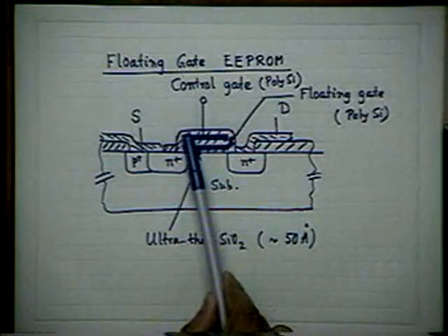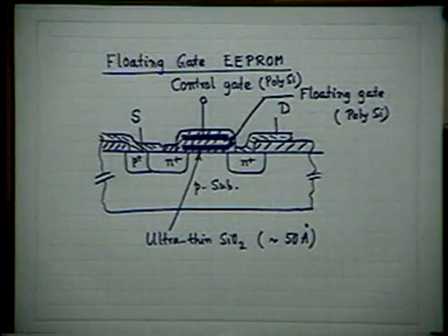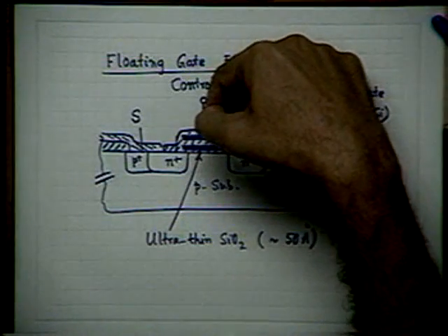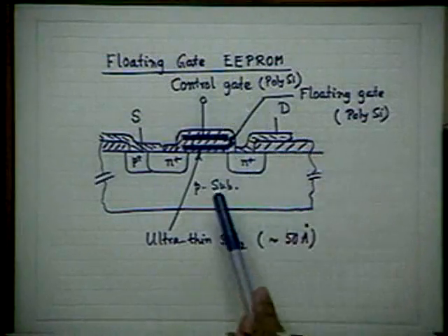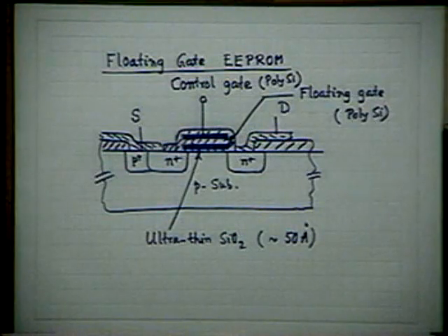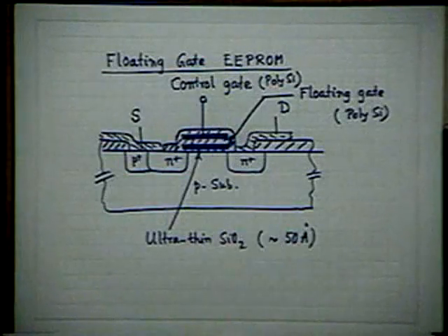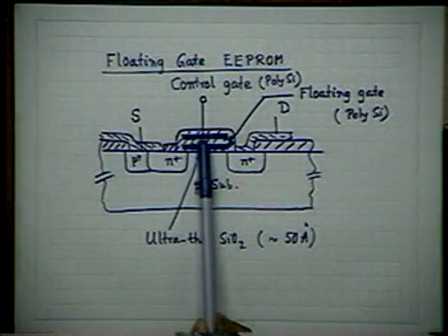And then the second gate, though in the diagram I have shown that this is also sealed, there must be some connection, because we never take the connection just over the device. We take the connection laterally over the thick oxide or field oxide. So it is not that this gate is accessible. There is a connection, but this gate is not accessible. It is totally shielded. And here also the same thing is going to happen. We don't use MNOS. Everything is oxide. Now, if we apply a high voltage here again for a short time, that will induce a strong field, because this oxide is much thicker.